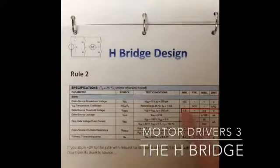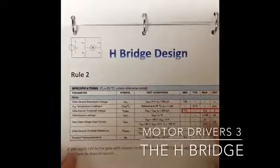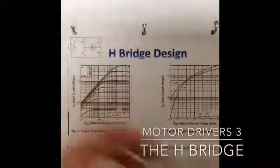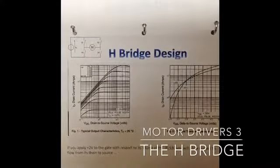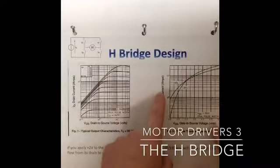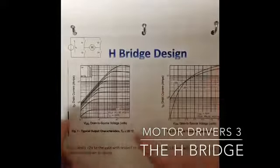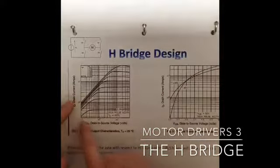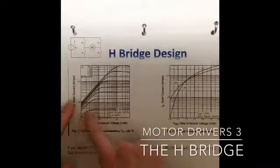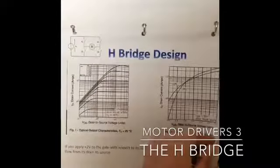If you apply, in this case, 2 volts to the gate with respect to the source, the IRL 530 will allow current to flow from its drain to its source. So you need 2 volts. So here are the typical curves for a VGS versus the ID current. So this is showing that essentially in a nonlinear fashion, the more VGS, the more drain current. And same here, you see the ID current versus the voltage from drain to source. It steps up and then it flatlines like a transistor curve, standard transistor curve, which I'm sure you're familiar with.